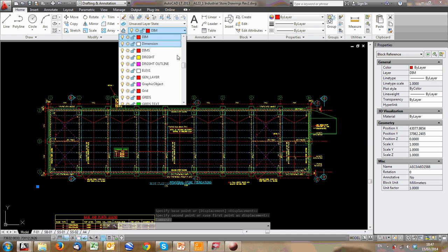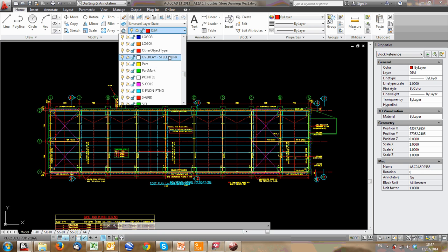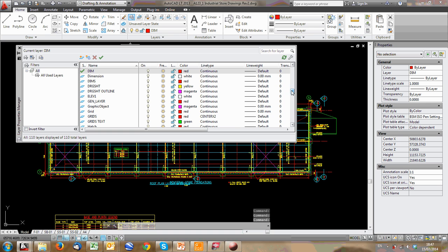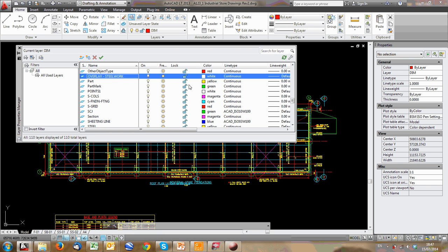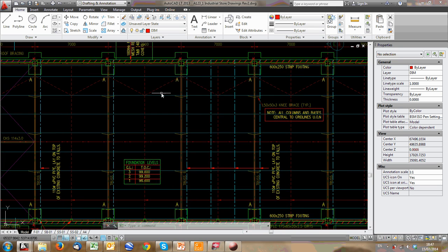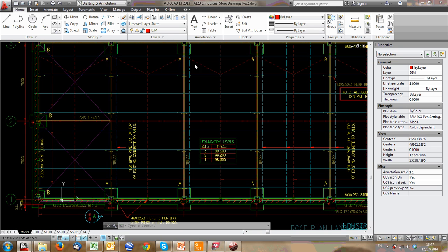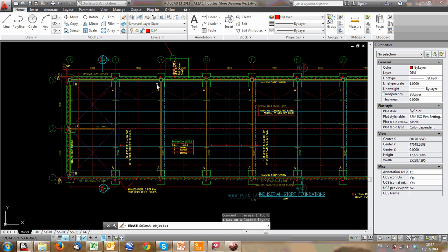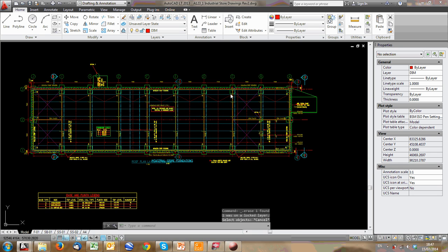So now I'm going to change it to the layer overlay steelwork. What I want to do now is lock that layer, and you'll see why I want to lock it when it's been done. So I'm going to go here, there's lock, overlay steelwork, and I'm going to lock that. Once you've locked something, it goes very faint and sits in the background. So now I can't edit it. If I'm drawing here, I can't delete it. I've selected it now, but I can't actually delete that layer. I can't do anything with it once it's locked.